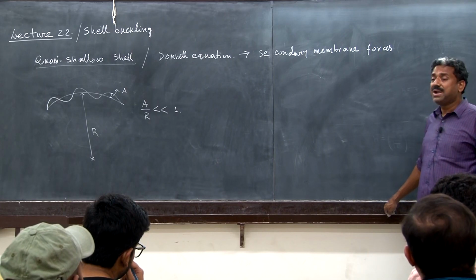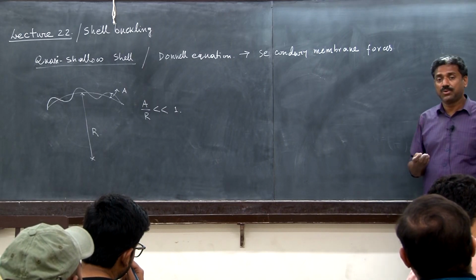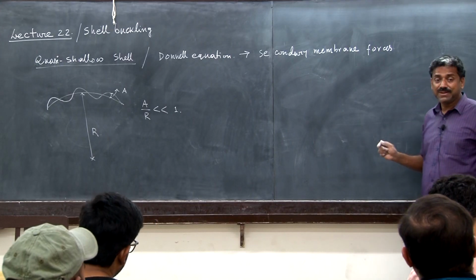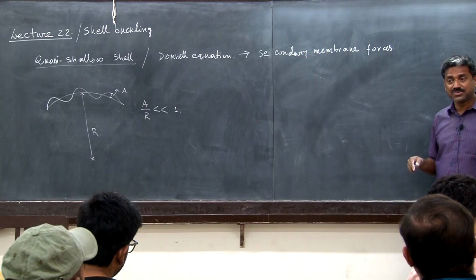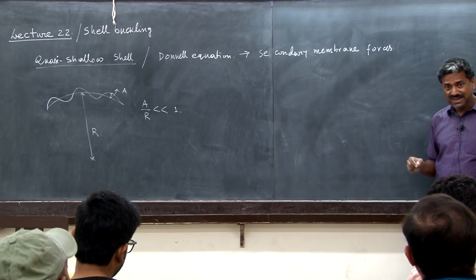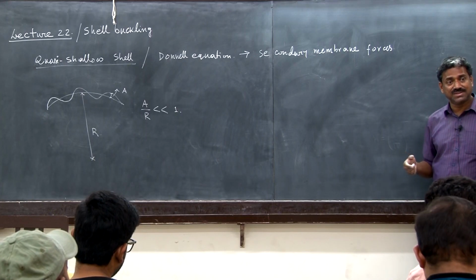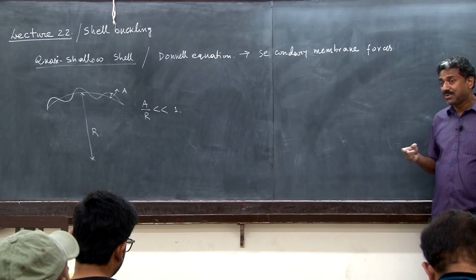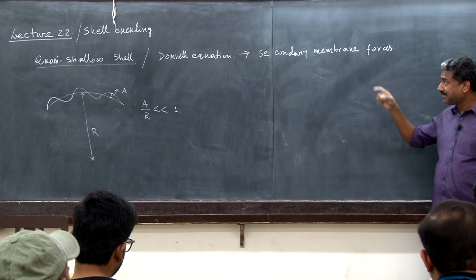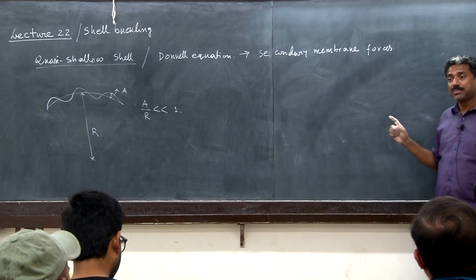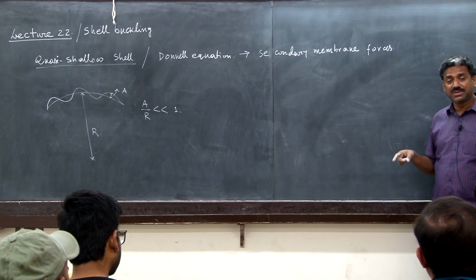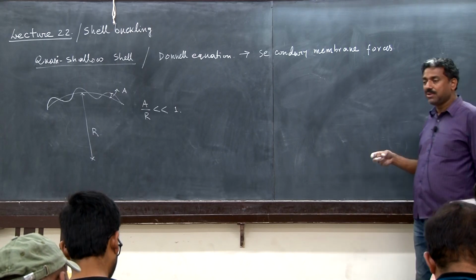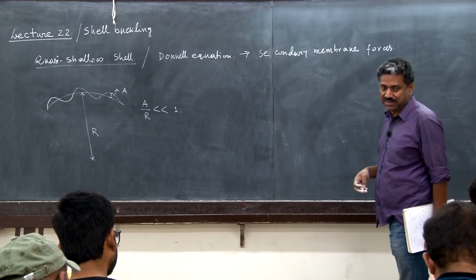But as soon as it buckles and moderate deformations take place, there is a redistribution of those forces, and because of that, secondary forces occur. And that's what we call secondary membrane forces. But here in the Donnell equation, in the shell, secondary membrane forces have to be considered along with the primary forces. You understand that, right? And why is that so? Because of this coupling, okay?